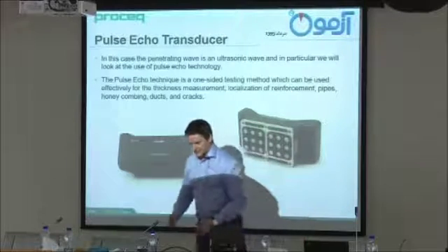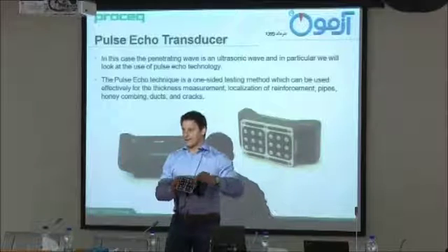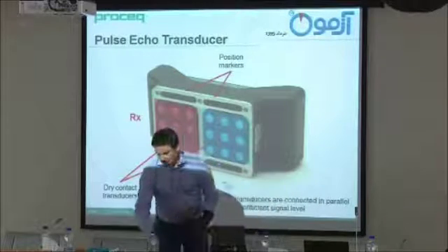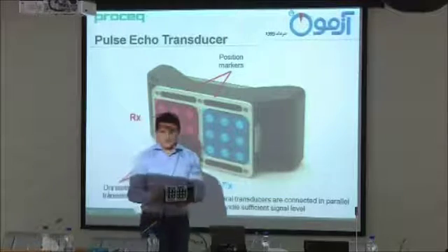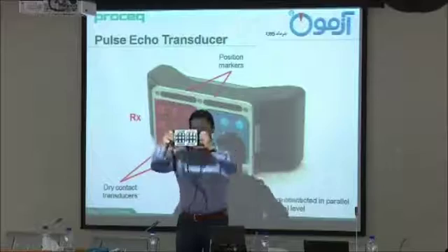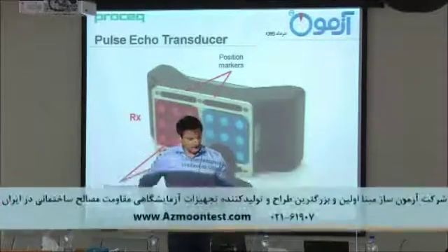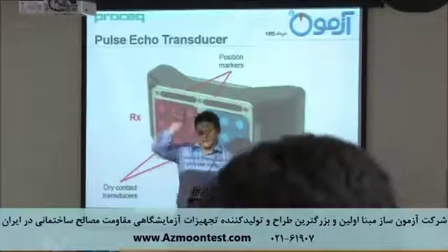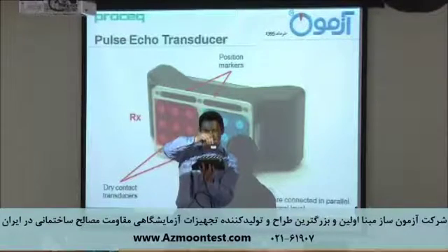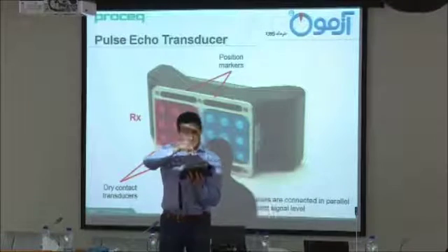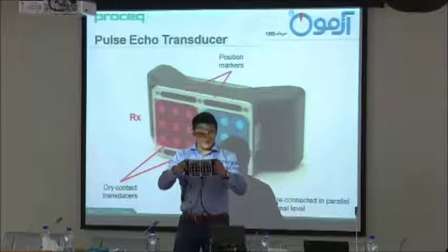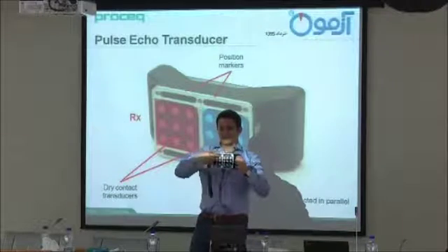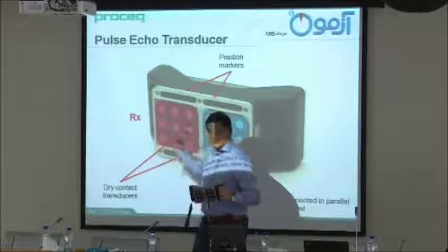When we talk about the pulse echo, we talk about this probe, spring-loaded, 9 transducers, 9 receivers. You can see here. For better understanding, you cannot go with the pulse echo this way. You won't get a picture. Why? Because like you see here, red and blue, transducer, receiver, it is all the time linked. This is the calibration plate, and then you have this together. So make sure if you use this pulse echo instrument, you go this way or this way, not up and down, because then it doesn't make sense. You have to have an overlapping, otherwise you don't get these images that we have seen.